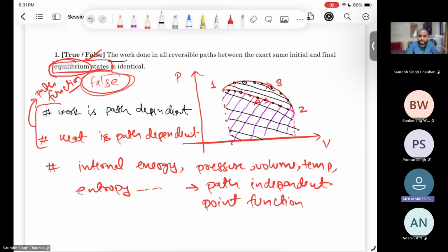Sir, if in any process the properties are changing, then this will not be applicable for that process. In any path, the properties will change, because path is connecting between two states. Properties are basically state functions; they are defining the state. So if you change the state, properties will change. We want to reserve the term path for the path, and state functions, the point functions, for properties.